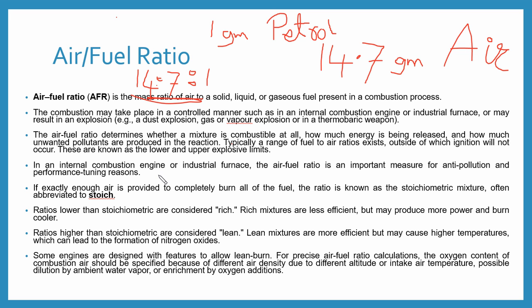If exactly enough air is provided to completely burn all the fuel, the ratio is known as the stoichiometric ratio, abbreviated as stoich. When the air and fuel ratio is lower than the stoichiometric ratio, it is called a rich mixture.